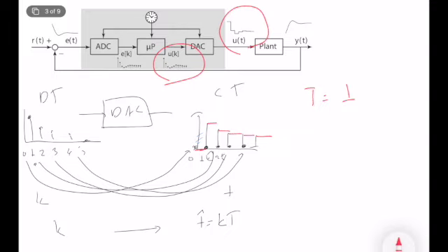This is important because in dynamical systems, of course, your output is changing. You are constantly producing voltage values, force values, or other kinds of control actions. And when any control action comes to your system, you change your output. Okay, so this is the output of the controller, and this is called a zero order hold operation.